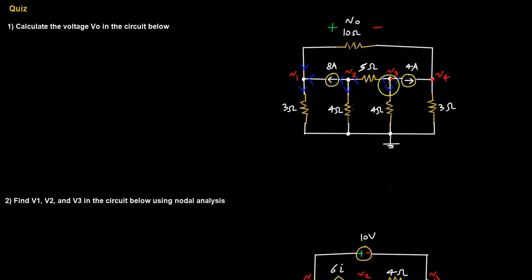No worries here that having all the currents come out, that should be no problem as long as everything is consistent. So I'm saying that the current's leaving that node, so I'm going to go this way. Now we're going to verify our directions, ensure that everything is consistent, and everything adds up. So let's go ahead and find the first equation, which is, let's see, V1 over 3 plus 8 amps is going to equal V4 minus V1 over 10.